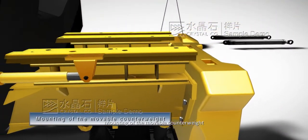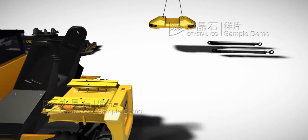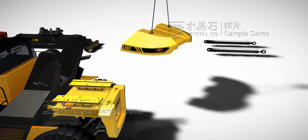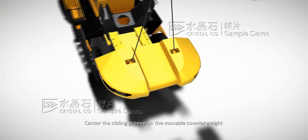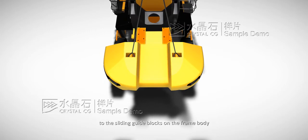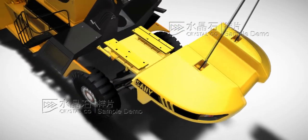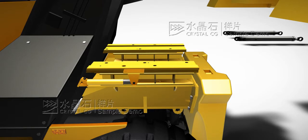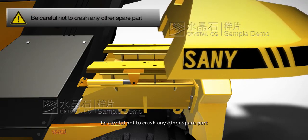Mounting of movable counterweight. First, remove the fixing tooling of the moving cylinder of the Reachstacker and lift the movable counterweight with a crane. Center the sliding groove on the movable counterweight to the sliding guide blocks on the frame body, and put the counterweight on the slide rail. Be careful not to crush any other spare parts.